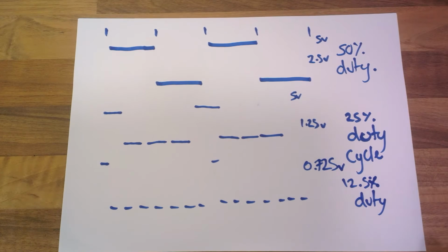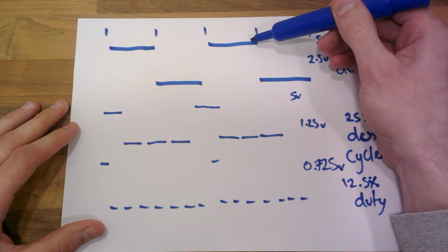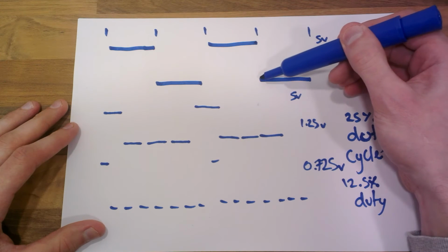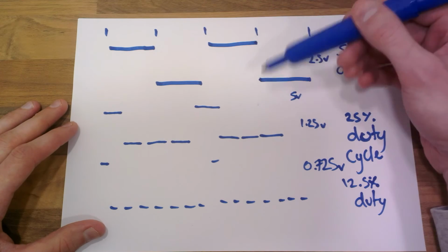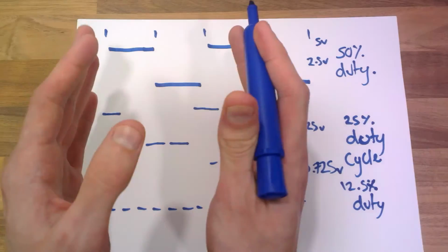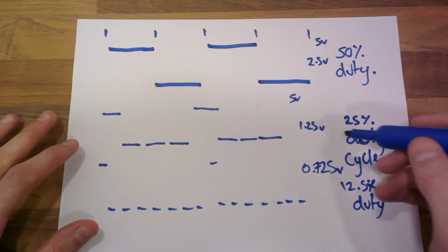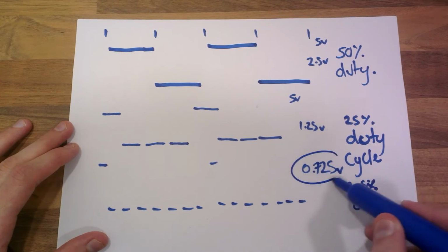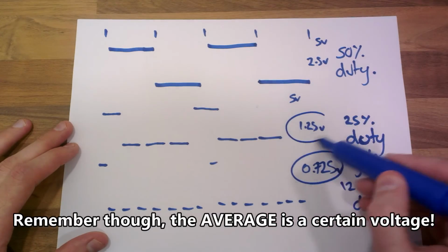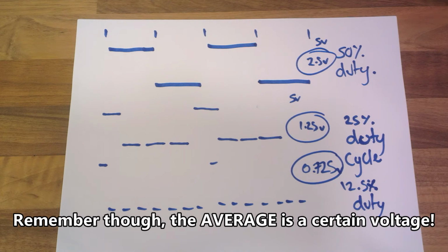And that's the way PWM works. So it's a percentage of time when 5 volts is high, and a percentage of time when it's low, 0 volts. And basically, this is pushed together. It's done really fast, and the resultant output is what I've just described. So in this case, it will be that. In this case, it will be that, and in this case, it will be that. Okay, I'm going to prove this to you now.